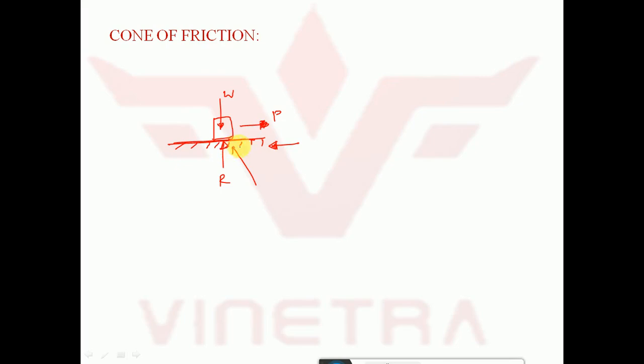Because of this frictional force and the support reaction, I can draw a resultant force R dash, which makes an angle phi. Let us take this point as O, and if I try to move this body in the left direction with the same force P, what happens? Because of this, there is again a frictional force developed opposite to the direction of motion. I will extend its line of action here, and this frictional force and the reaction again make a resultant R dash, and it makes an angle phi here.